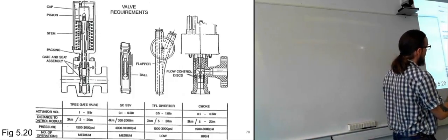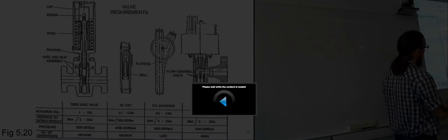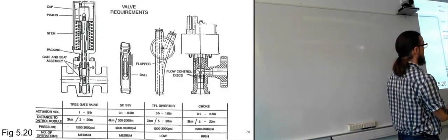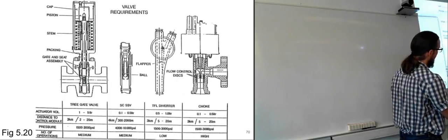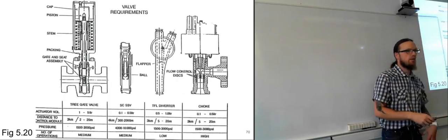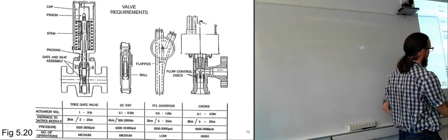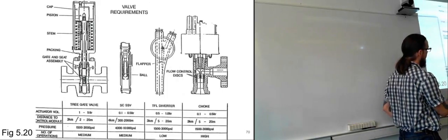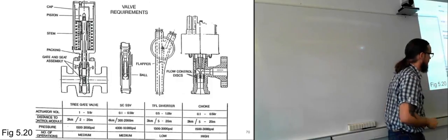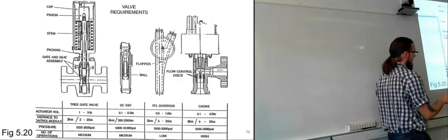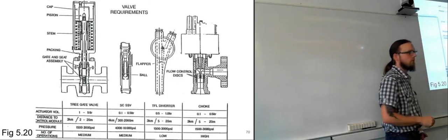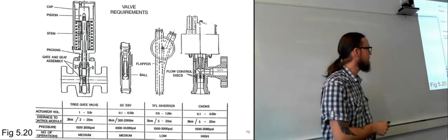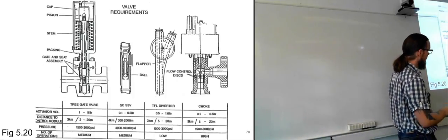So we also have the surface controlled kind of valve, the surface controlled subsurface safety valve. And this is the one where we have a flapper, which will flap closed if we don't have hydraulic pressure, so that it will swing up here and just close off the entire area, unless it has a certain amount of pressure coming in. And as you can see, this is a lot less, so the piston isn't really all that big in this one. So it's 0.1 to 0.5 liters, so that's not much, just a couple of deciliters.